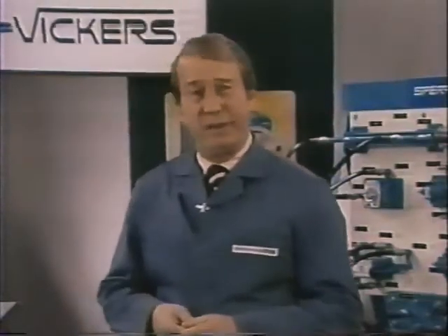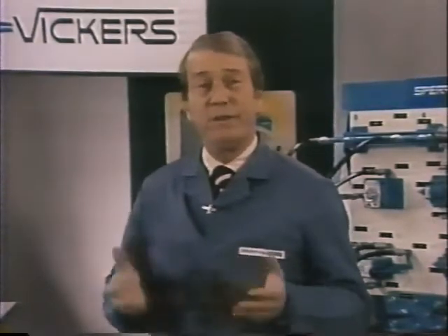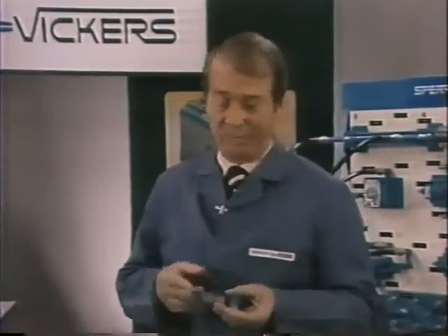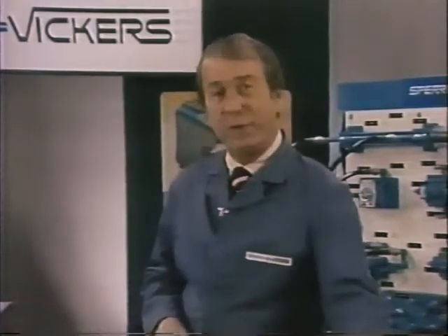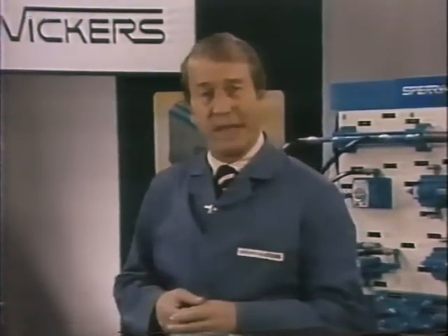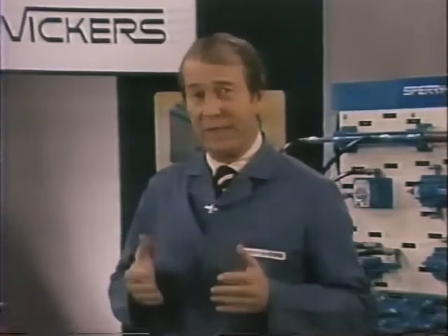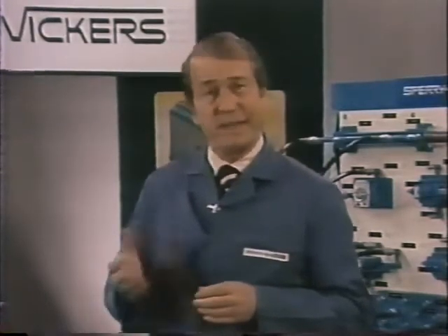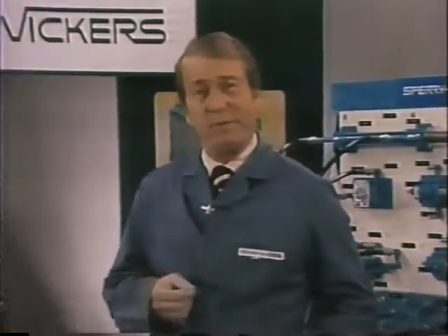Now, let's take a look at a situation where the workload changes. The valve that we've been using up to this point is just a plain old needle valve, something like the faucet on the side of the house. Let's say we have the flow control adjusted for 5 gallons per minute. The other 5 gallons go over the relief valve at its setting. The pressure at the relief valve is 1,000 psi because that's where the valve is set. The pressure at the cylinder will be determined by the workload.